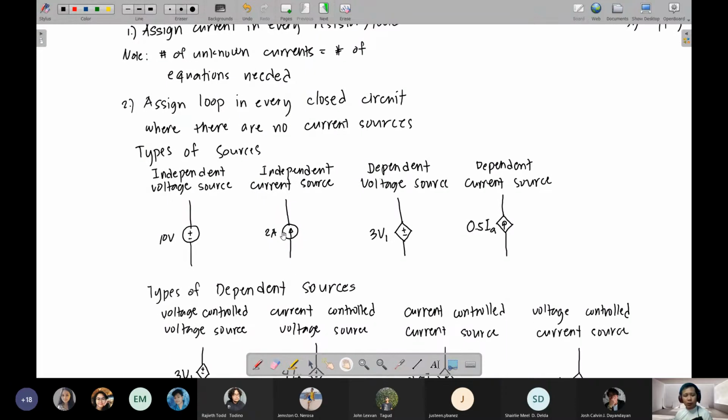So in that moment where you have no voltage, you need a voltage, which is why you apply KVL. So it's not necessarily that you cannot, but it complicates things because you are forced to assume. For example, you apply KVL there and there is no voltage, you cannot use 2 amperes because that is not a voltage. So you just assume, for example, that this current source has a voltage VA.